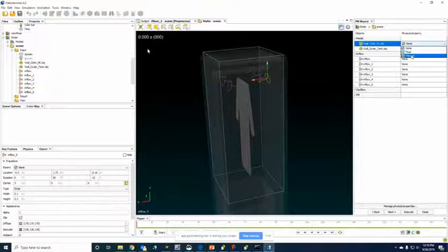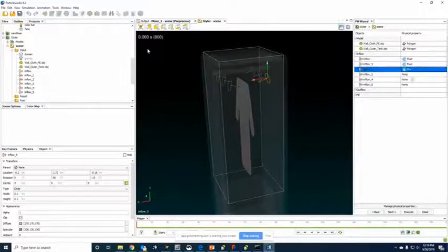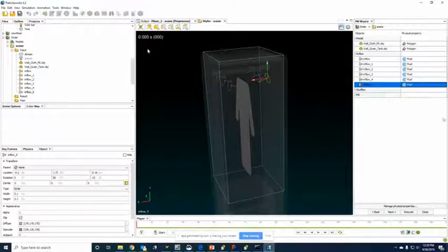So I want to change both of these walls to polygons, and I want to change the inflows to fluid. If you had a second fluid in there, you'd have multiple options that you could select from the properties that you defined previously. But the basic idea is that you first define your properties, and then you associate them with the inflow in particular.